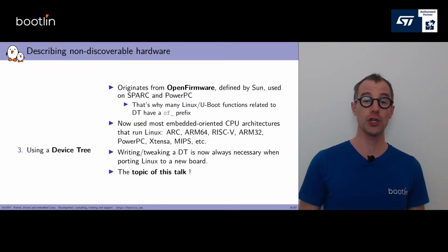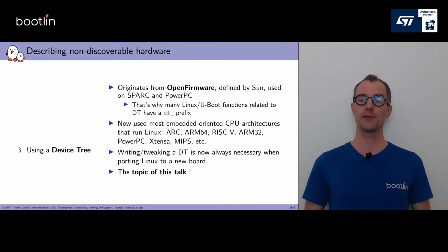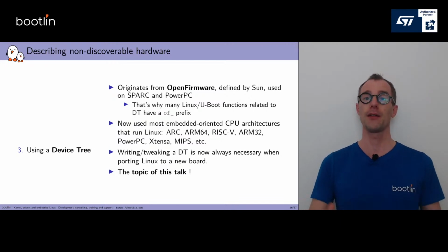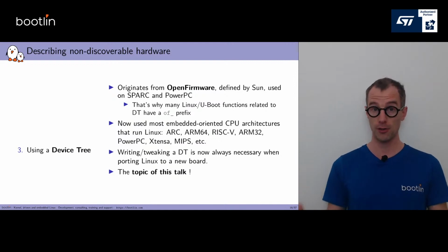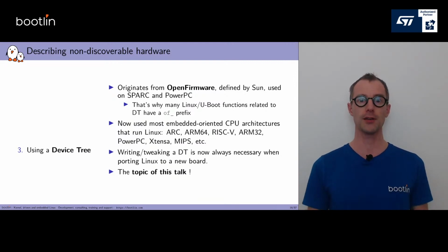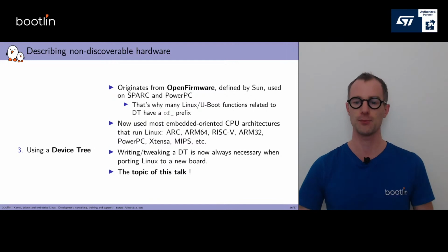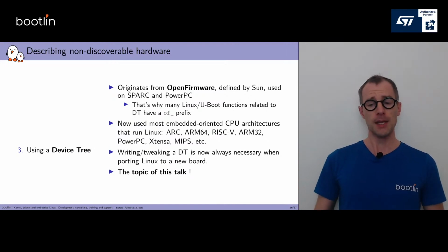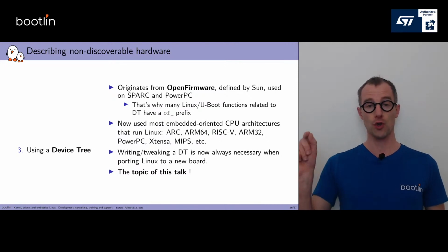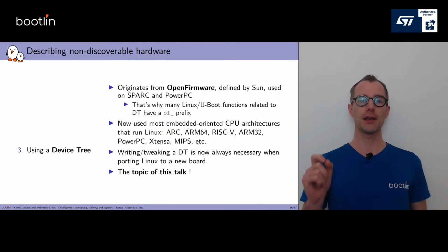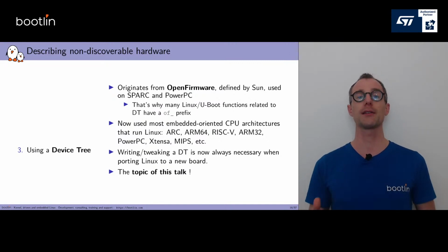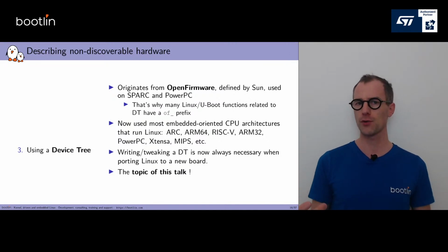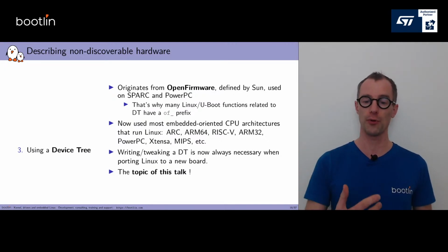It's something that originates from open firmware, which was defined by Sun Microsystems, used on the SPARC architecture, and then on PowerPC. So it is not a technology that comes from the Linux community. It is really something that has been used before. And this name, open firmware, is sometimes reduced to just OF, and that's why there are many Linux or U-Boot functions that are related to device tree that have this OF prefix. Which is sometimes confusing when you don't know that it relates to open firmware.